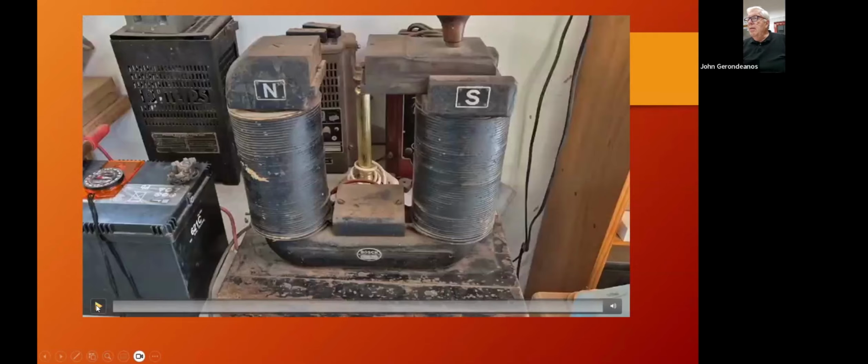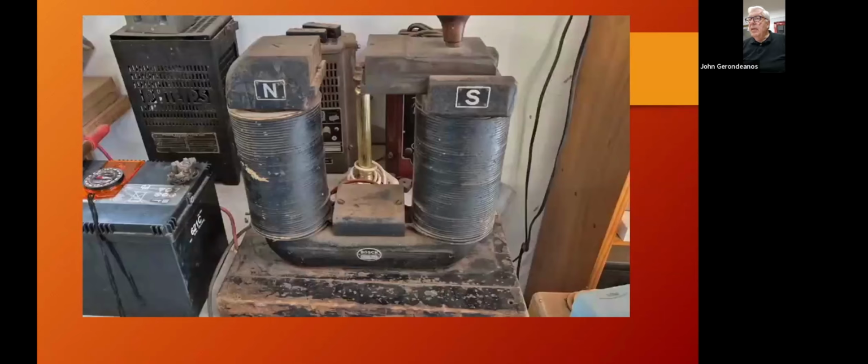And then let's get on to building a magnetizer. So when we want to build a magnetizer, we need to understand some very basic principles. When you plan a magnetizer, you plan the ampere turns for it. It involves calculating the necessary magnetomotive force, and this is fairly simple. It's the current times the turns.